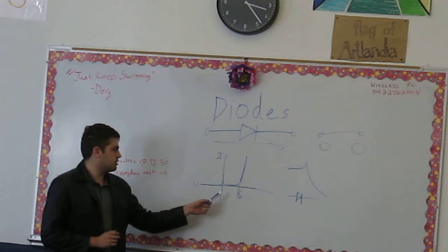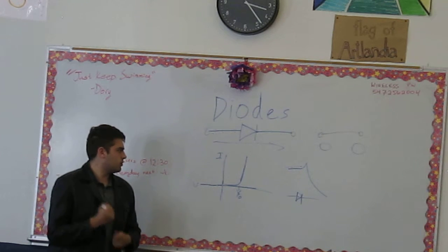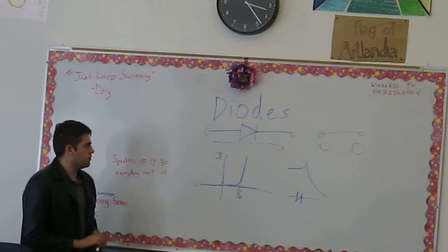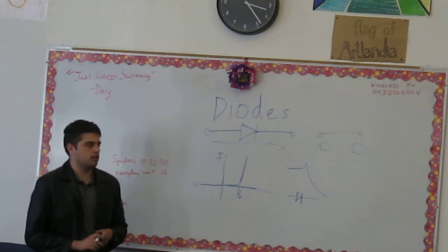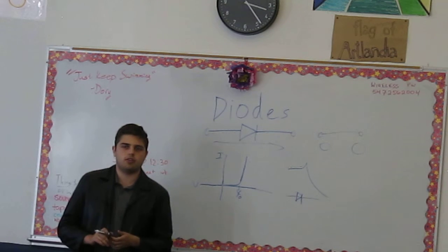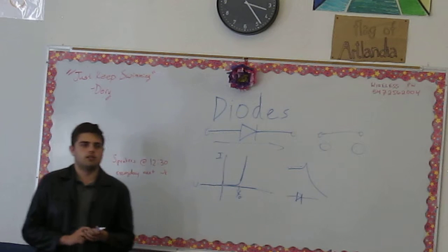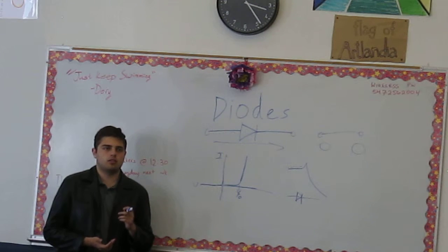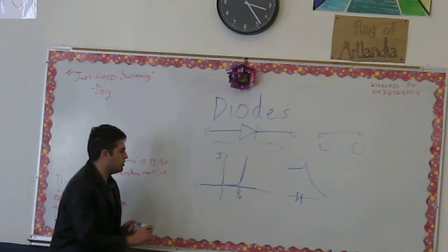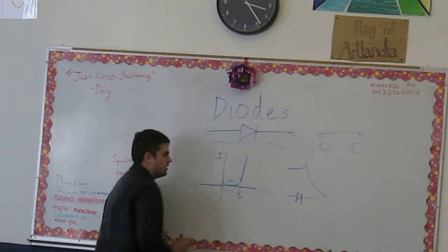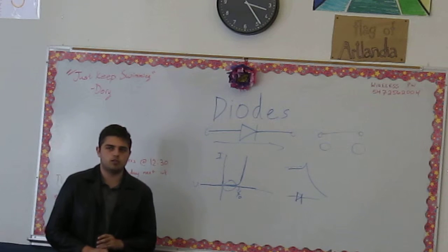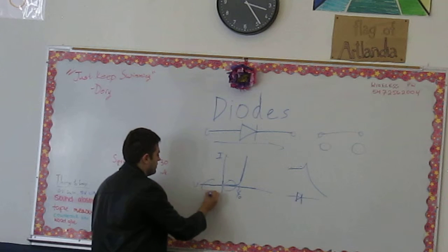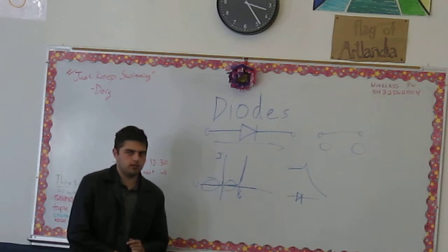So what this means is, let's go through some cases of you troubleshooting your circuit. You've got a circuit with an LED, and let's say you hooked it up and you turn the thing on and it doesn't turn on. What could be wrong? Voltage isn't high. Yeah. So you could be living in low voltage land, where it's not turned on yet. What else could be wrong? Yeah, you could be in negative voltage land. Both those cases, you have not enough current.